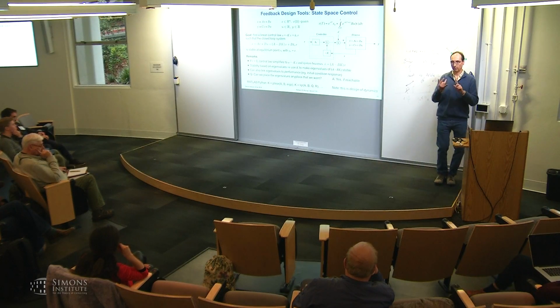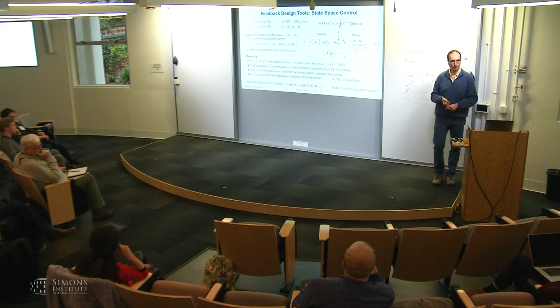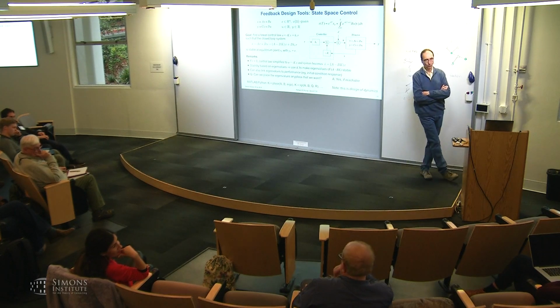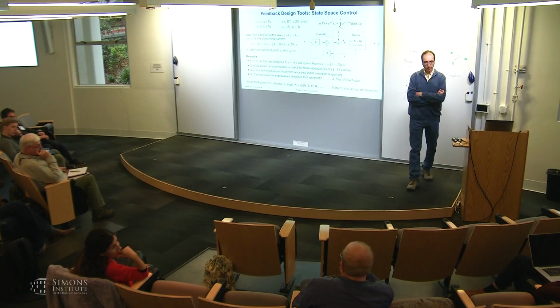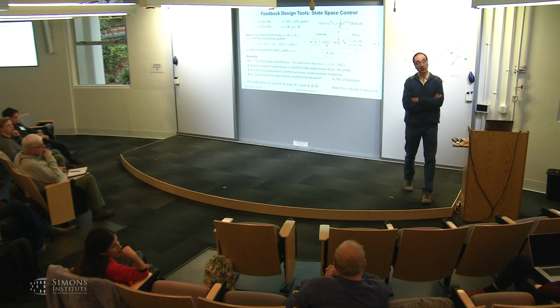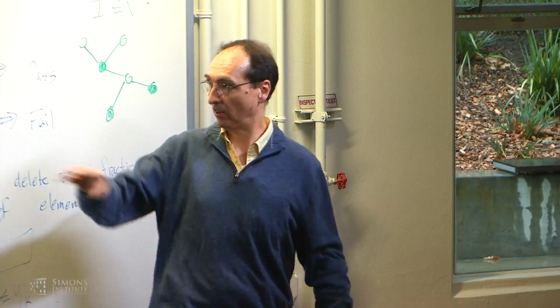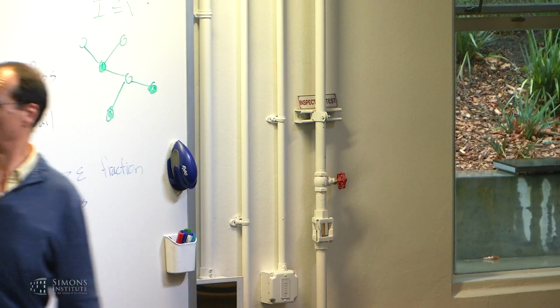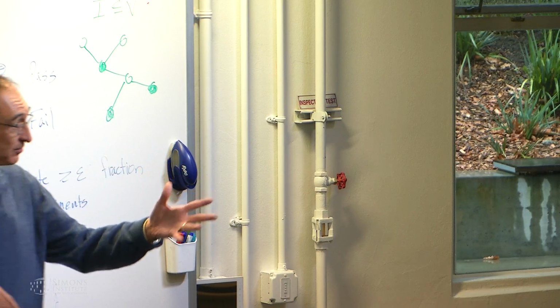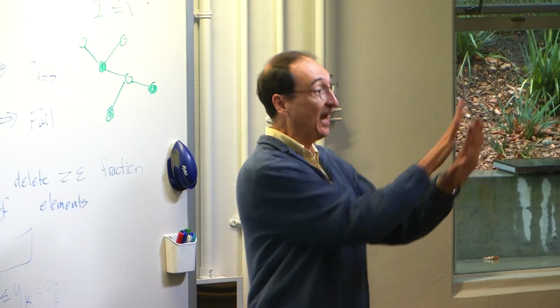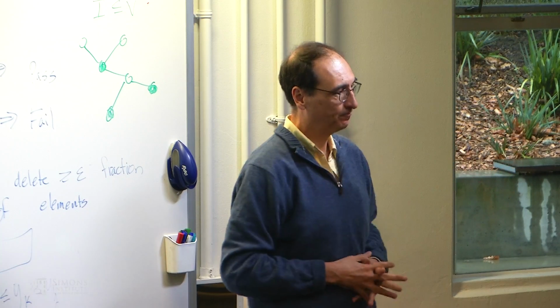But other questions on PID or state feedback? Yeah. If I have such a complete description of the process behavior already anyway, can't I easily do the planning, or trajectory planning? You could, assuming that there's no uncertainty. Okay. Right, so again, you put in the feedback to compensate for the uncertainty. The eigenvalues, if I have some uncertain dynamics, so that A matrix isn't quite the A matrix, in fact, I could have an A matrix that went between stable and unstable, but A minus BK might always be stable, for example. Yeah, good question.